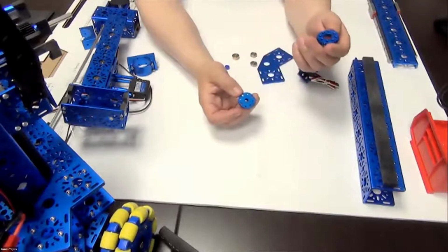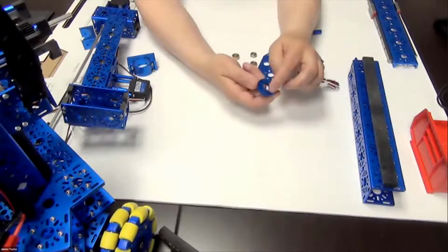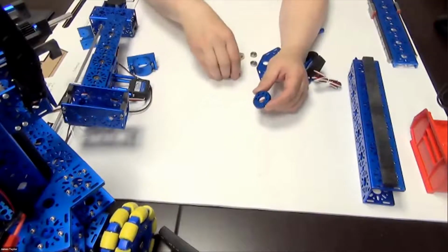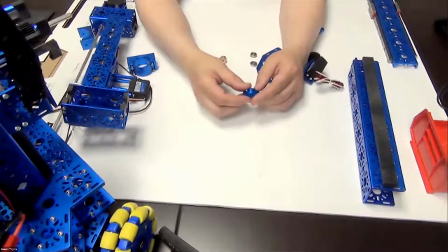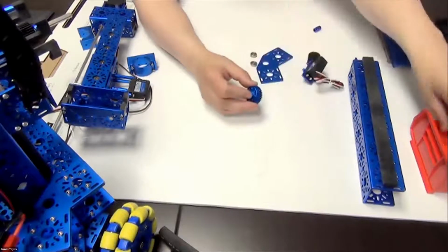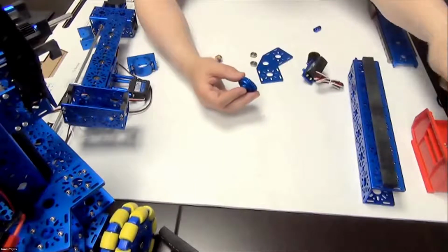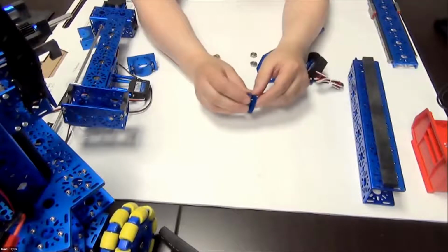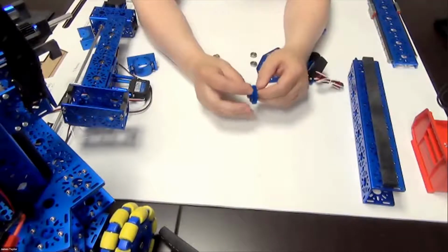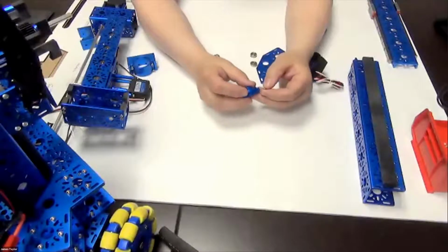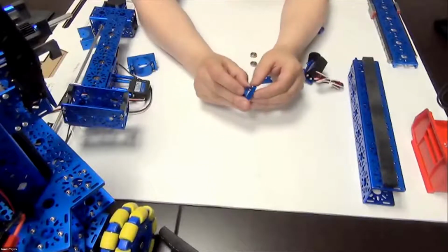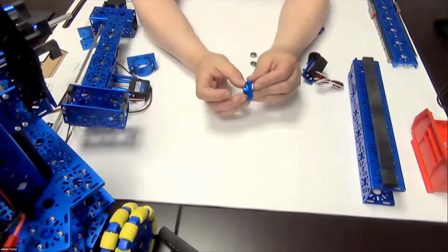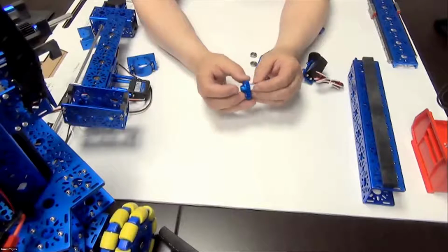When you're going to attach the gears, the gears have through holes on them, and when you're doing the shaft hub, what you can do is simply put the shaft hub over, and you can run through the through hole on this side into the threaded hole this way. So you go through the through hole and into the threaded hole, and you can attach that hub to the gear for the drive mechanism.